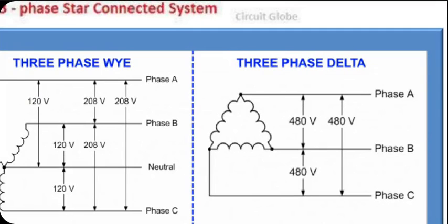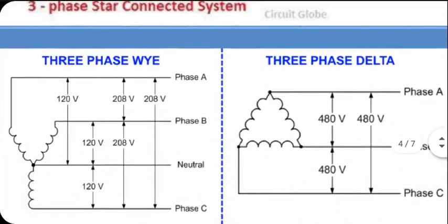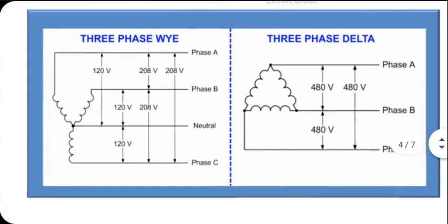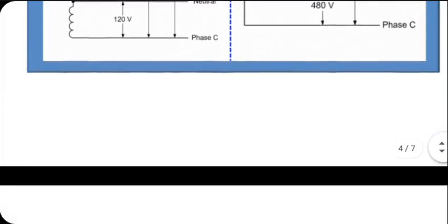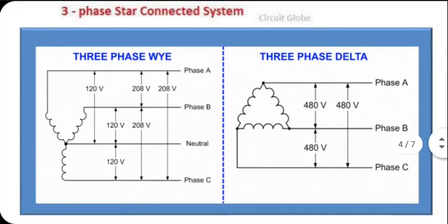Here also 120-degree phase shift is maintained, but behavior is quite different because of the way the connections have been made for the generators. Here only 3 wires come out and they are known as lines. No neutral is possible for a 3-phase delta system. Star system versus delta system, there are pros and cons. Engineers always debate which one is better. What I know is that in real life, both of them are used depending on the situation involved.